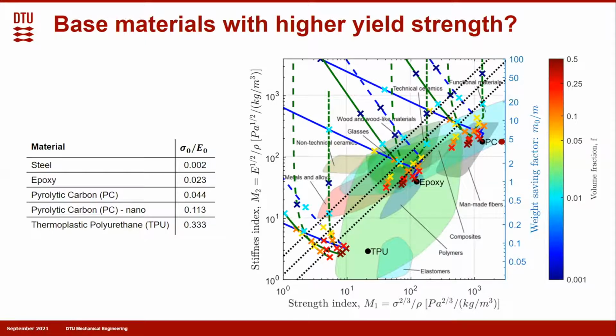However, the general observation is still validated here, which means a long span beam favors open cell truss lattice, and a shorter span beam favors closed wall plate structures. But for the transition variations, they are due to the different yielding strength to Young's modulus ratios.